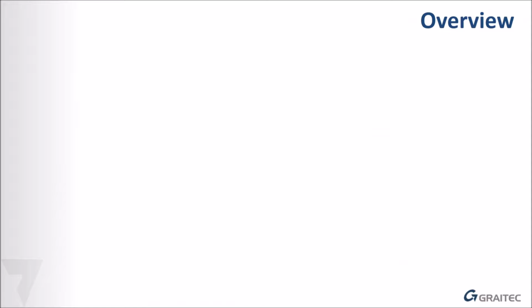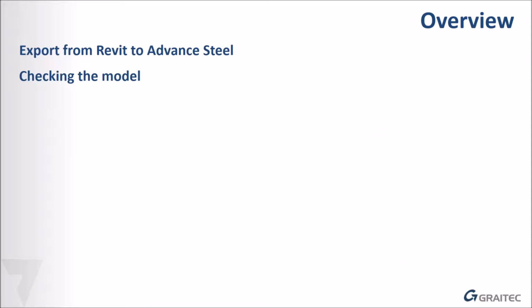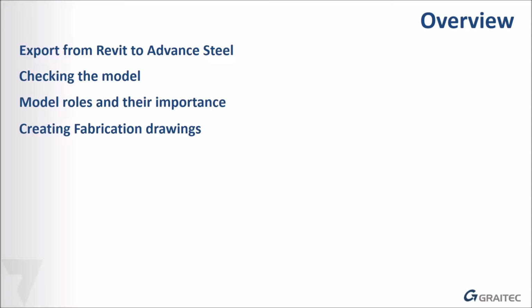What we're going to look at today: I've completed my Revit model with all my connections, so I'm going to export it and then import it straight into Advanced Steel. Then we're going to look at the tools in Advanced Steel for checking the model. Then I'm going to move on to model roles and their importance. These drive the numbering and the drawing output. Then we're going to create our fabrication drawings and run our schedules, and I'll show you 5 different schedules that I always used to run for clients. And then we're going to look at the NC and the DXF output.